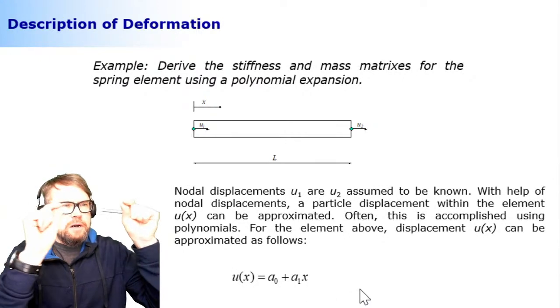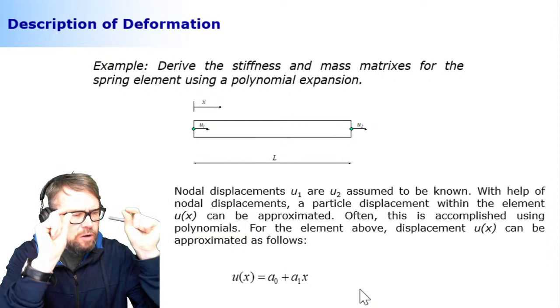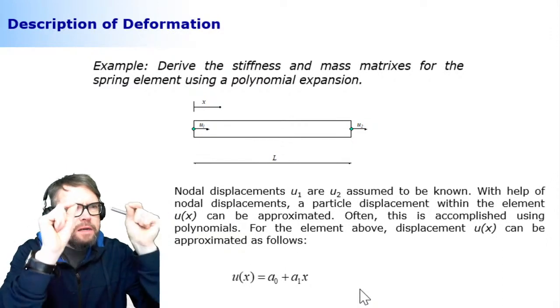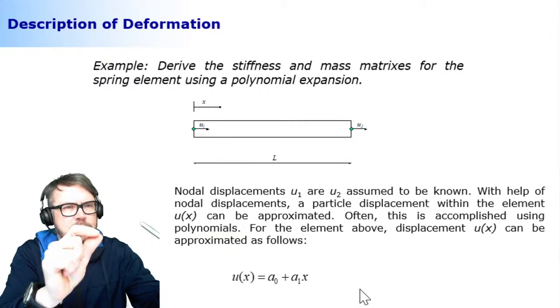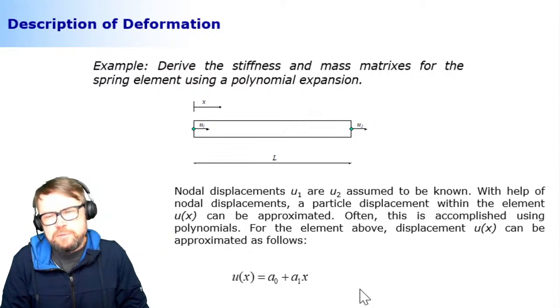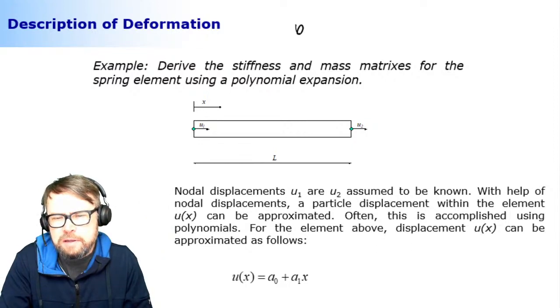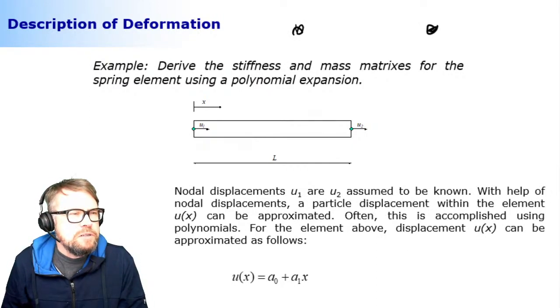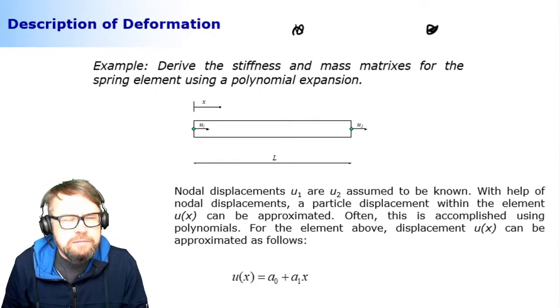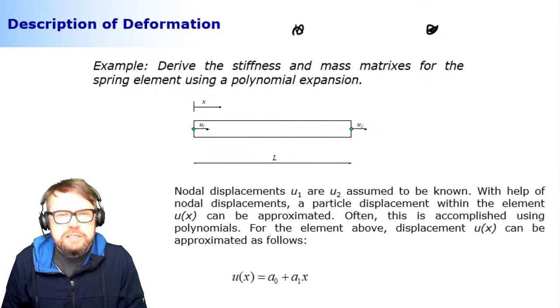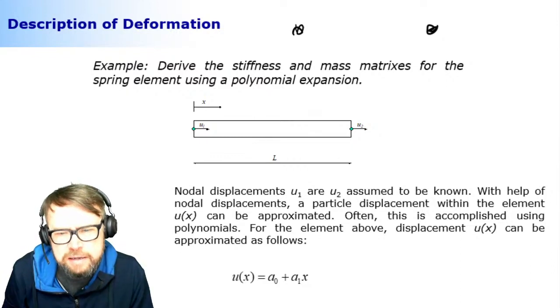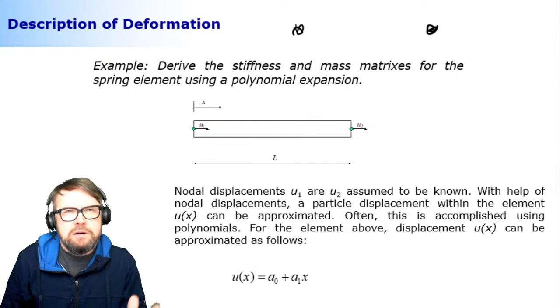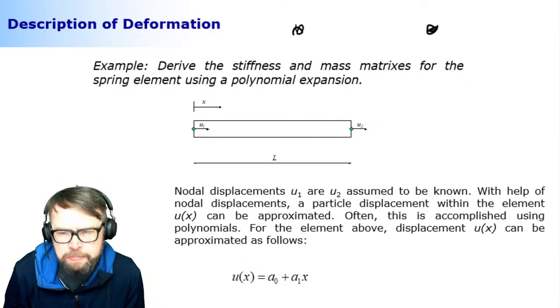All right, so I was about to explain that the finite element method is all about how particles behave between these nodal locations. It means that if you have a beam element that has 2 nodes, you have to make some kind of approximation of how the particles between these nodes behave. This tells how good or bad your finite element method, or element to be more specific, is.